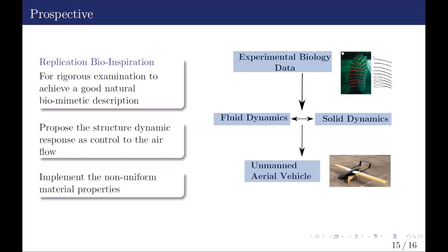Okay, good question. Actually, the method here, the coupling here, I started with a one-way coupling, which is I solved the simpleFoam, and I get the converged state of the fluid flow around the wing that I will take and couple to the solidsFoam solver. So this is an initial simulation to see the response of the solid to this data from the fluid. But next we have to do a dynamic way, which is after solving the fluid, you give us two-way.